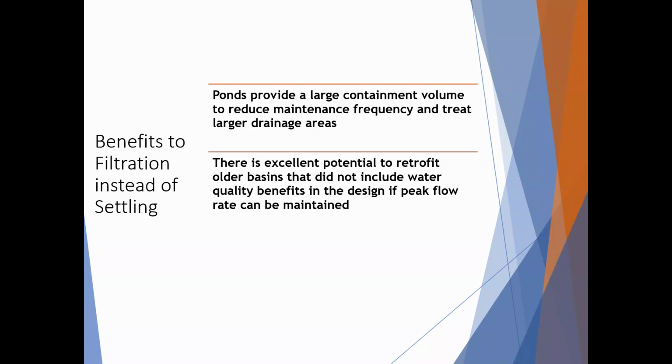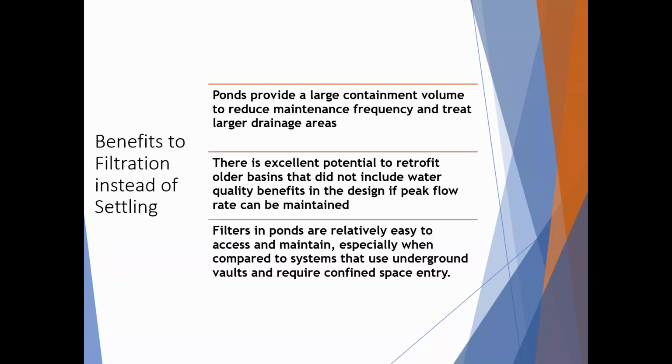So if we try to incorporate additional volume in there for settling, to hold that for an extended period of time, the basins tend to overflow. So that's not really typically an option. But if we do it with filtration, and our filtration rate keeps up with that low storm event rate, so typically a 2-year storm, then that's an excellent potential to retrofit that basin to meet water quality.